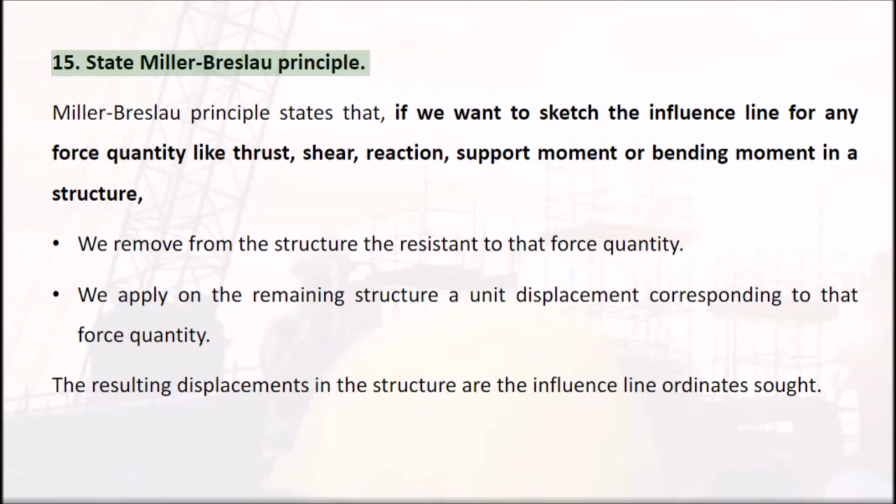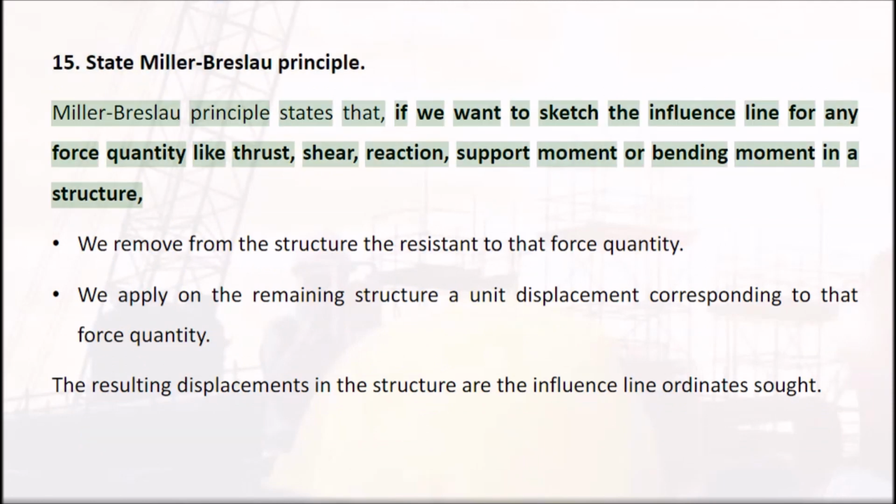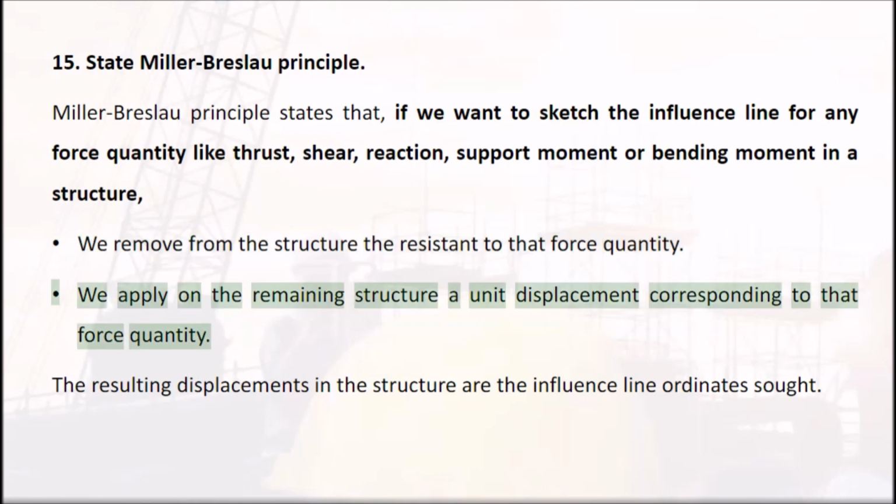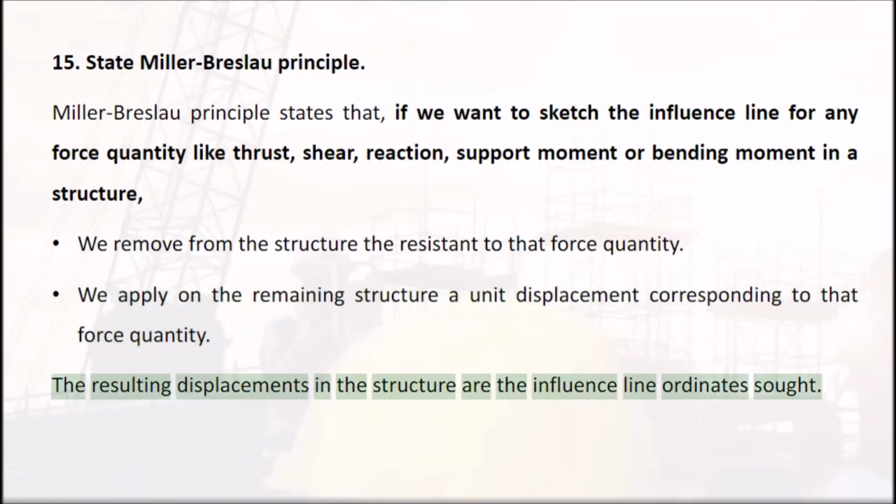State Miller-Breslau principle. Miller-Breslau principle states that, if we want to sketch the influence line for any force quantity like thrust, shear, reaction, support moment, or bending moment in a structure, we remove from the structure the resistance to that force quantity. We apply on the remaining structure a unit displacement corresponding to that force quantity. The resulting displacements in the structure are the influence line ordinates sought.